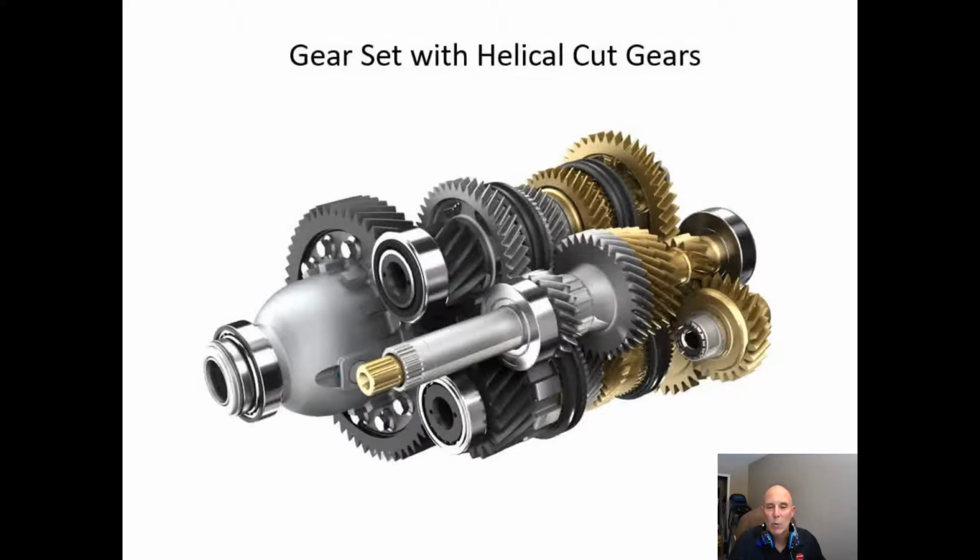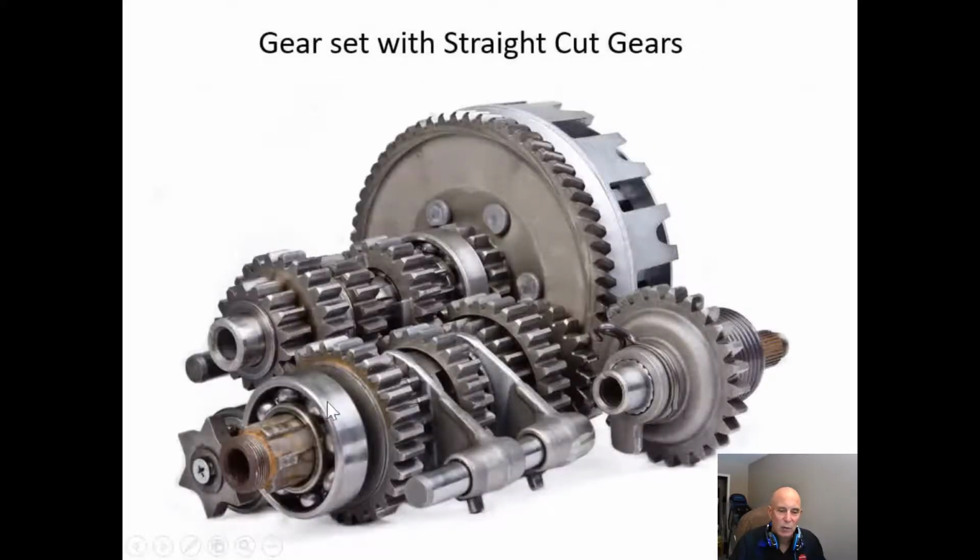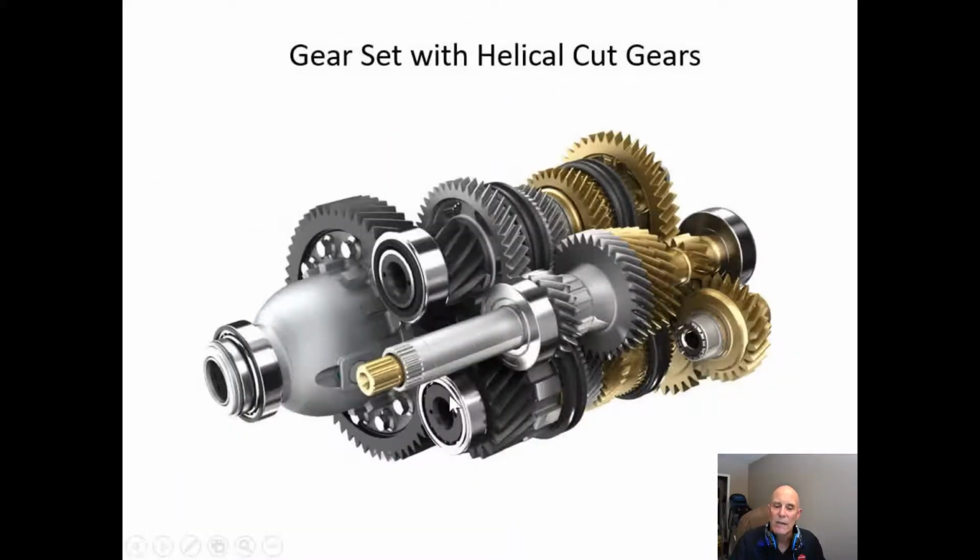Now, if you remember from when we were discussing bearings, we can have a straight roller bearing, and if we go back and take a look at this here, we have straight roller bearings here because all we have are radial loads forcing each other apart. But when we start having axial loads in here that are pushing one way or another way, we'll use tapered roller bearings. Now, anytime that we have this type of a shaft, we have to shim these bearing cases.